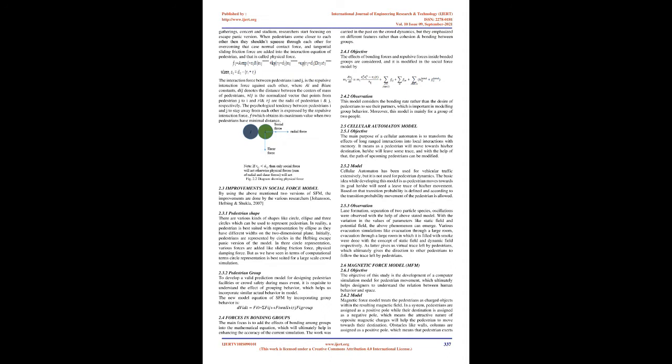The main objective of the pedestrian studies is to assess the effects of a recommended policy on the pedestrian facilities before its implementation. The objectives are to extract the reliable pedestrians' trajectories data from a video recording of a crowded street after removing noise using appropriate noise reduction techniques, and to validate and calibrate the social force model with the real-world pedestrians' trajectories data obtained from a crowded street.